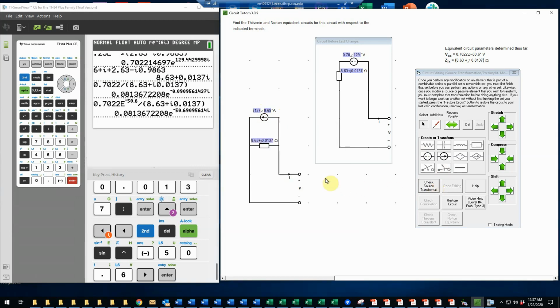Okay, so it's telling us the polarity of the transformed source is incorrect. And indeed, because I used the VOC value, and again, that was wrong, I should have been using this value. So I made another mistake. What I can do to fix that is simply change the polarity. That's the easiest way to fix that rather than bothering to change the angle, and that will fix it.